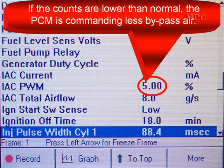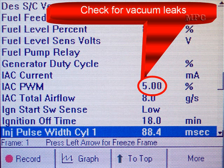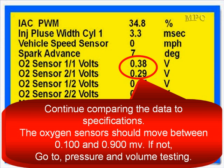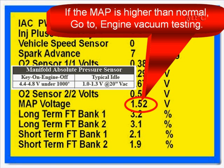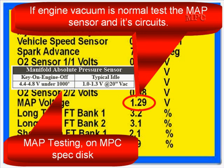If the IAC counts are lower than normal, the PCM is commanding less bypass air, so check for vacuum leaks. Continue comparing the data to specifications. The oxygen sensors are going to be moving between 0.1 and 0.9 volts. If not, go to fuel pressure and volume testing. The MAP sensor should be within specifications. If the MAP sensor is higher than normal, don't forget, it may be good, so you want to check engine vacuum. Go to engine vacuum testing.